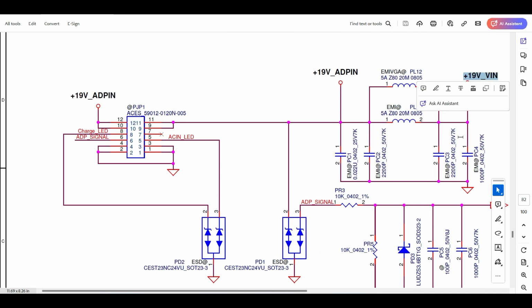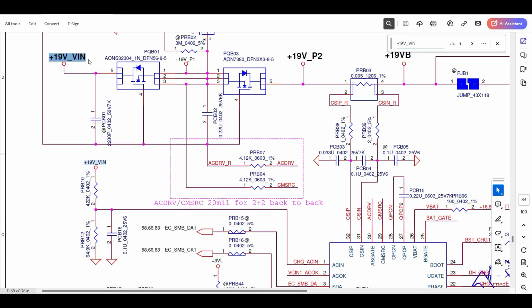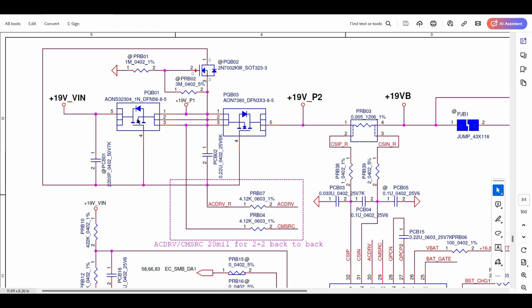Now the source we got, 19 volts V in, will come from the source. See, this 19 volt source is connected to the drain of the first MOSFET. Okay, so here it has come, here it's a drain concept, or drain to source it won't go. When will it go? Here it should get the gate voltage, some particular gate voltage, which we call the threshold voltage.